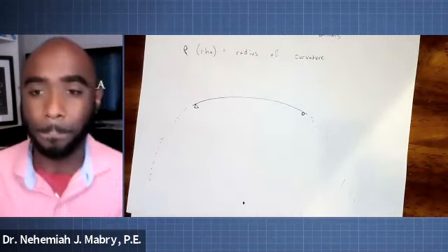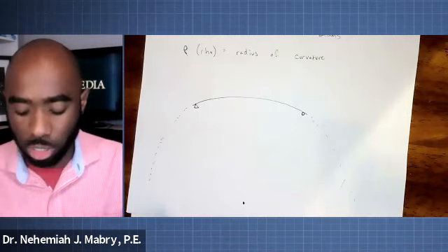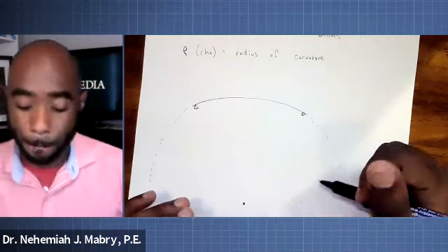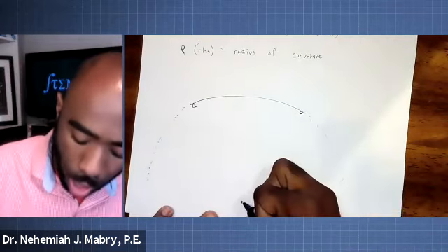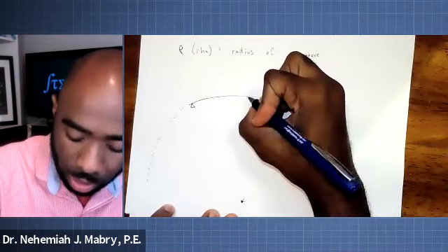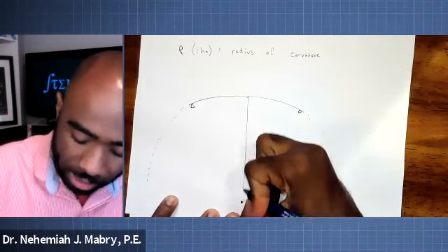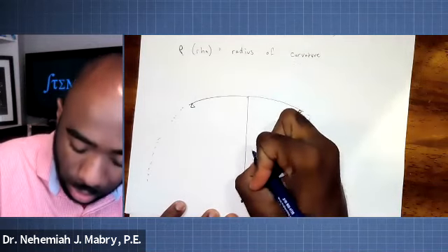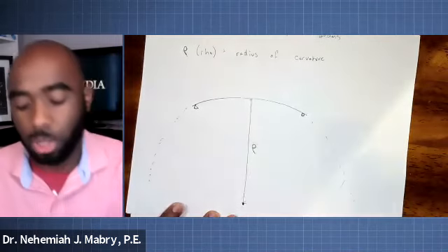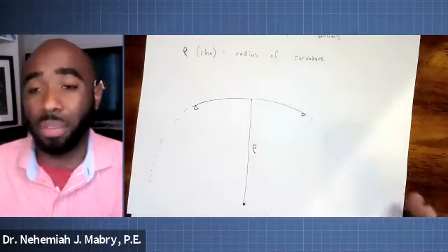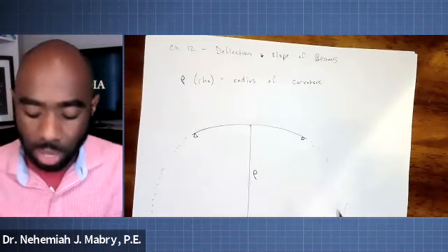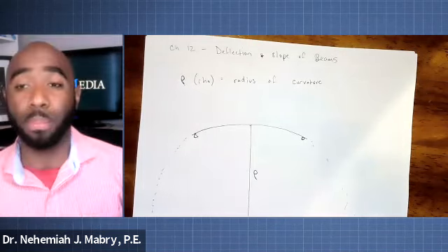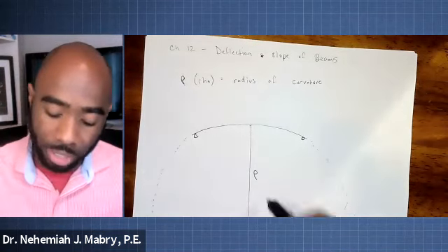Well, that center would also give you a way to determine a radius of that circle. That radius is what we call the radius of curvature, right? So the radius of that massive imaginary circle, for which this exaggerated bending beam is a part, is denoted by rho.